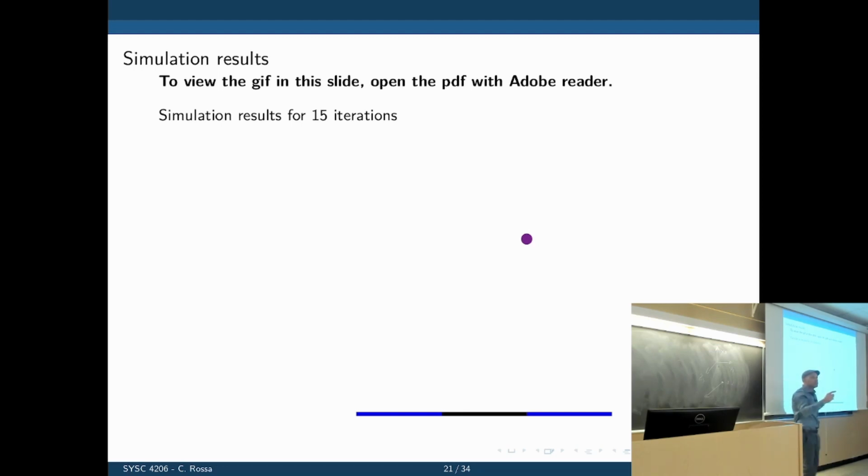Now, be very careful here because people sometimes confuse this with what the robot is doing. This is not what the robot is doing. This is you looking for solutions to bring the robot where you want. You wouldn't give the robot commands for every step of the iteration. It doesn't make sense because you know that you are far away from it. You will run this several times. Once you find your solution, then you only give that position to the robot.